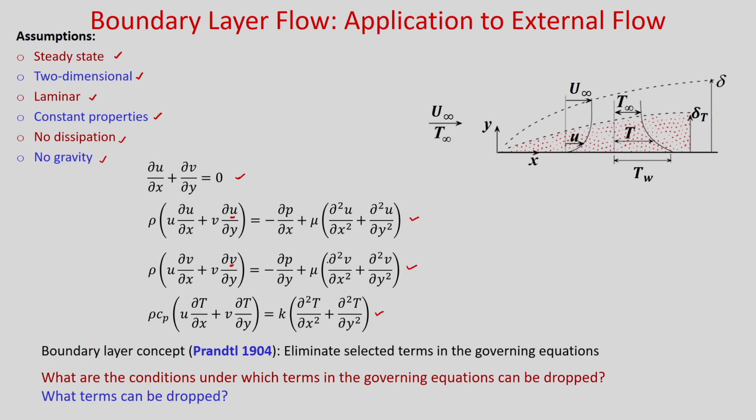So, in today's class we will use the boundary layer concept, and we will see if we can drop some terms from these equations for boundary layer flows. The scientist Prandtl actually used scaling analysis and showed that a few terms in the governing equation can be dropped, because those terms are very small compared to the others.